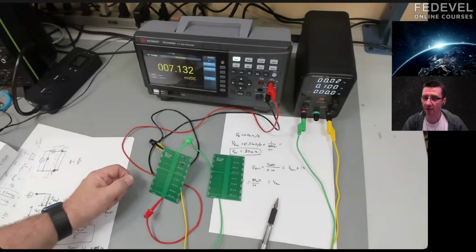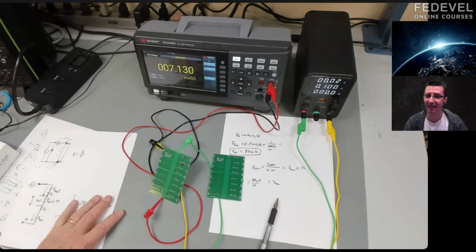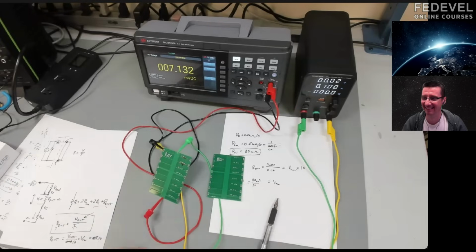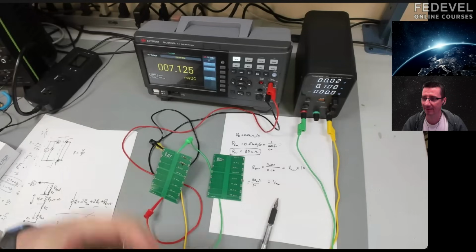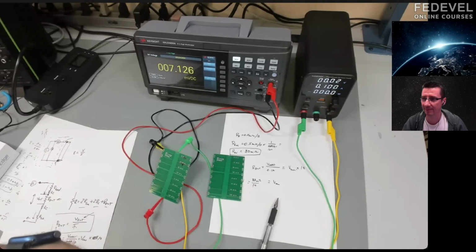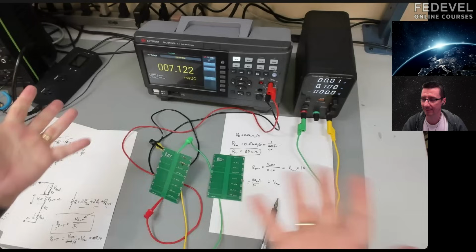So this way you can also kind of verify how good the PCB manufacturer is, how consistent the PCB manufacturer is. So measuring sheet resistance in general is a really important number to know for your board. And there's some techniques that we could literally use that 100 mil wide trace to do that because that's 10 squares. We measured a resistance of like 3.5 milliohms for 10 squares. Hey, that's 0.35 milliohms per square. That's the sheet resistance of that board. And that's one way of getting it.